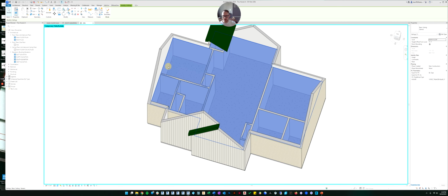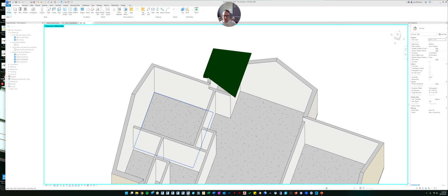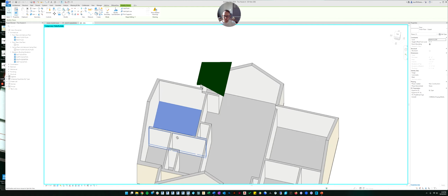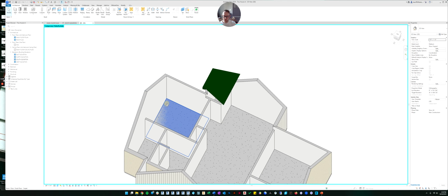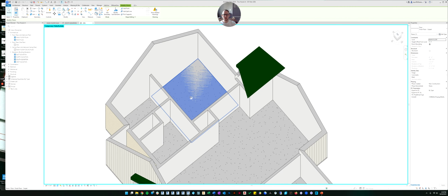And we also need to hide our ceiling. So we'll hide that temporarily. And now, oh, it's hard to see. But do you see how when you select the floor, you get that weird fuzziness when you move it around? It's because the floors are exactly the same height.